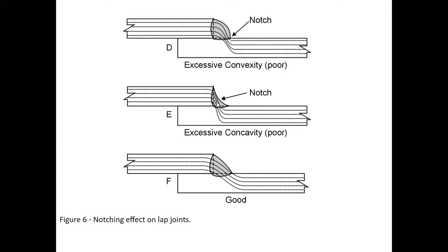right here. So if we got these lines a lot closer together here, that's going to cause that notch effect. That's where that break could happen. So in a weld like this, we got a 3/8 plate, 3/8 effective throat on the weld, 3/8 plate. We see nice flow, all the lines are even. So we don't want to create that pinch point right here. That's basically what we're looking to avoid. Any spot where those welds are going to be forced, or the stress lines are going to be forced together, that's going to be a place that may see some failure.